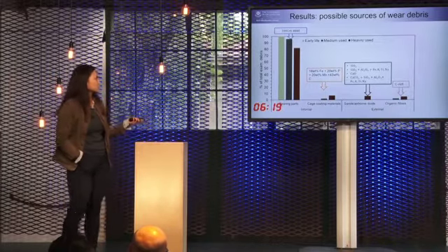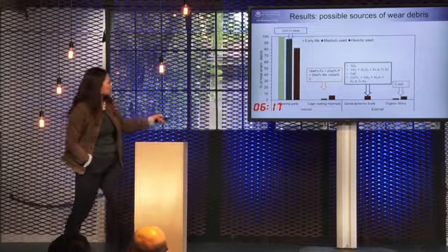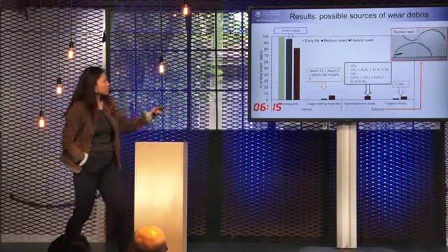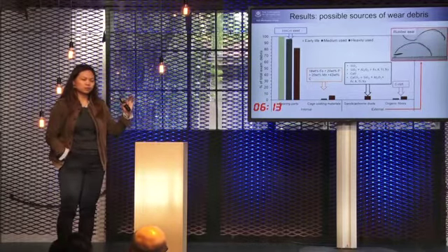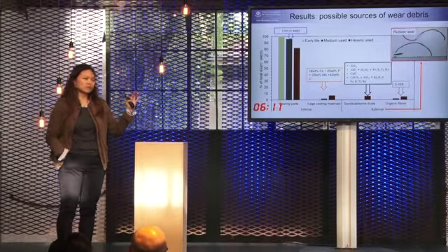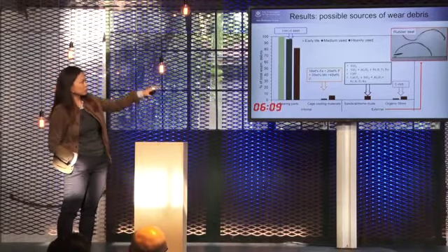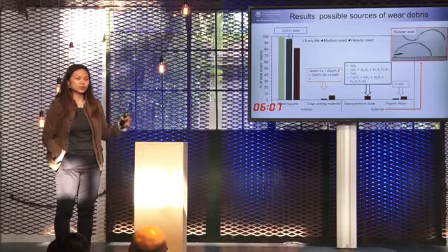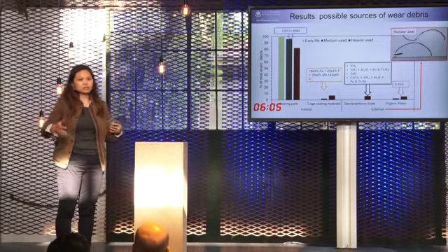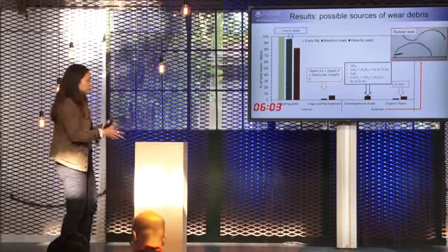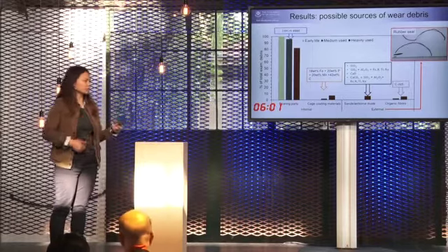In this case, we found that the external debris was only found in the heavily used bearings, and we think this is because there is a lot of seal degradation happening. We found a fragment of the seal in the heavily used bearing. That gives us an indication that external debris has a chance to come into the contact area.